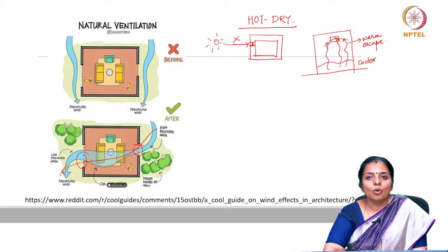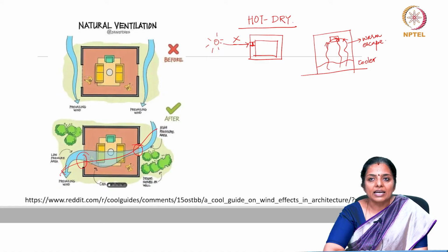Low windows allow ground reflected light. Light being reflected from the ceiling provides the most uniform illumination. The middle located window, in comparison, distributes neither skylight nor ground reflected light well. Some basic thumb rules can be followed in the positioning of the windows to enhance air movement.